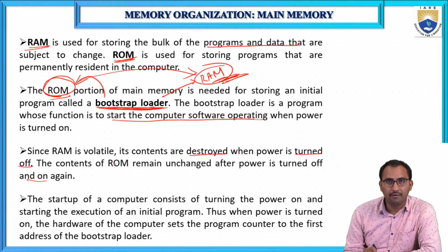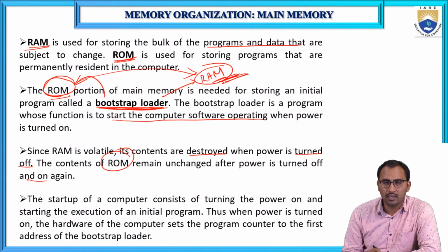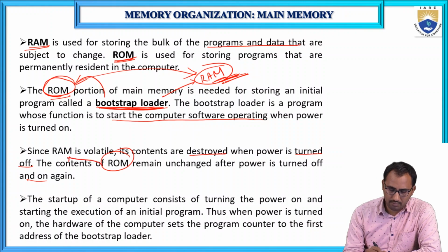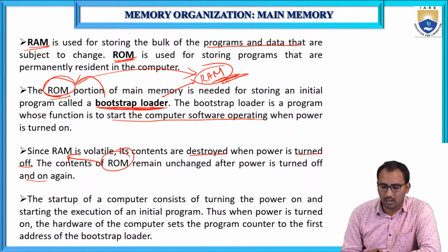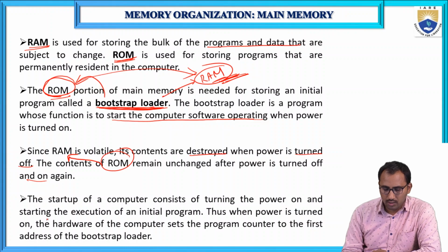So that's why we are storing the bootstrap loader program in the ROM, and that bootstrap loader program will be executed from the RAM. This is the reason why we are not storing the bootstrap loader program in the RAM memory. The startup of a computer consists of turning the power on and starting the execution of an initial program.